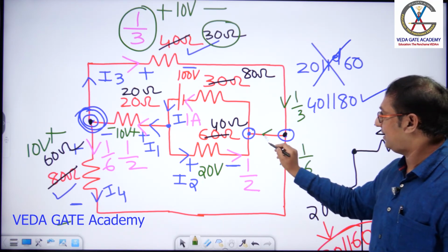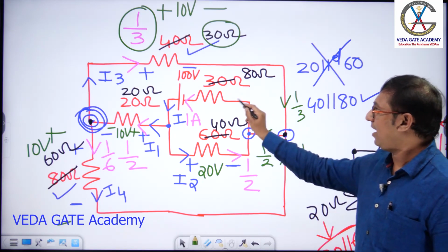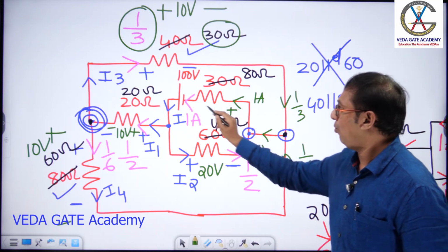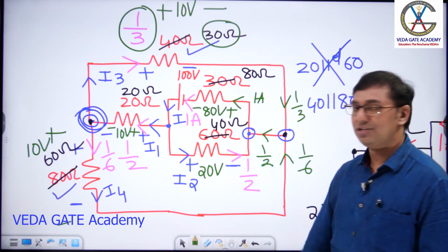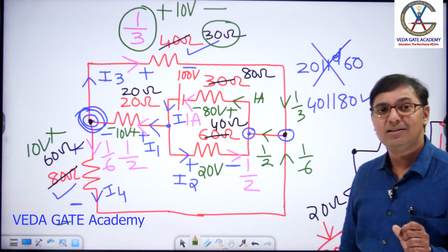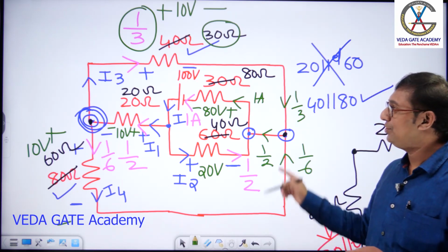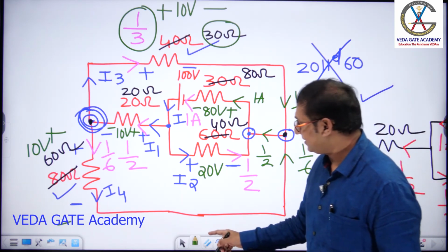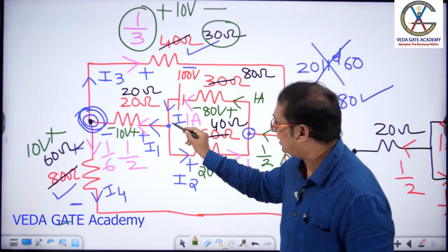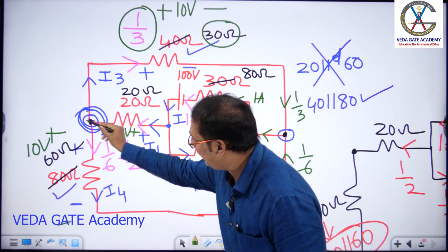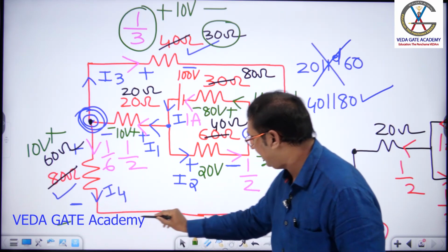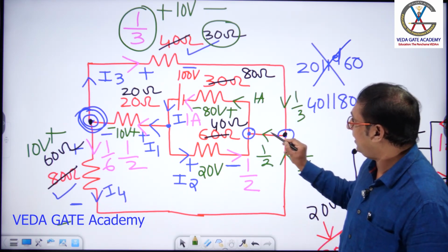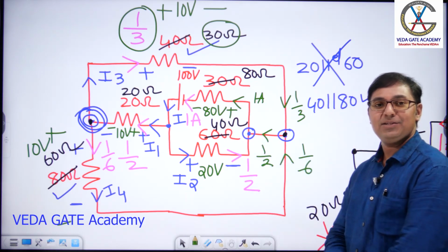Simply. So now please, 1/3 amps coming like this, 1/6 amps coming like this. This is half. Half and half adds like what? 1 amp. What is this voltage, sir? 80 volts. Shall we verify KVL? Sir, do this problem 2 times. You will write much faster than me. Clear here? Come on. Right? Yes, apply KVL: 100 equals to. What is the voltage here, sir? 10 here plus 10, 20. Here 80. KVL satisfied.